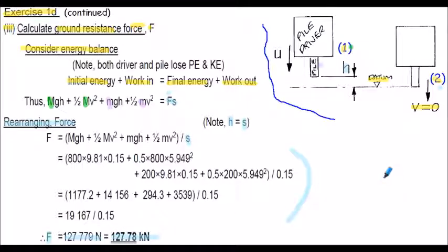So you can see this pile driver problem is quite a complicated problem, and we're analysing it in 3 stages, applying energy methods first of all to find the velocity on impact, linear momentum methods to find the velocity after impact, and then energy to find the work out of the system and essentially find the force applied to bring the pile to rest. I would encourage you to revisit exercise 1D at your own pace, fully understand the solutions, and then attempt the questions shown on the following slide.